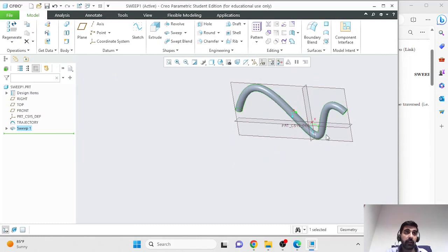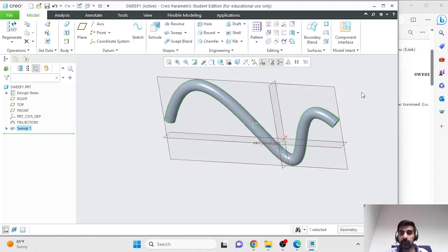And if you want to make unconventional profiles, which are not perpendicular to a cross section or which are not actually symmetric, you can use the sweeping command. You couldn't have made, or you couldn't have easily made something like this using extrude or revolve. I would argue you can't make these using extrude or revolve. That's how you perform the sweep operation.